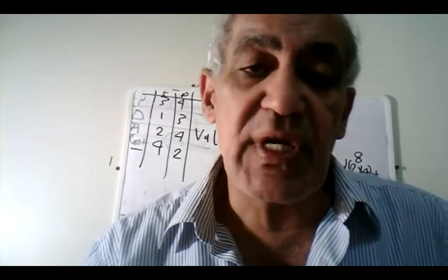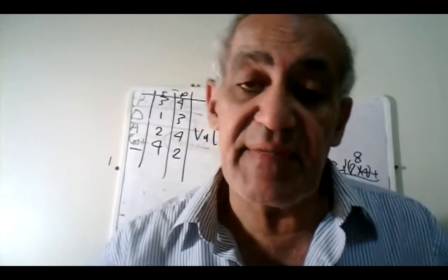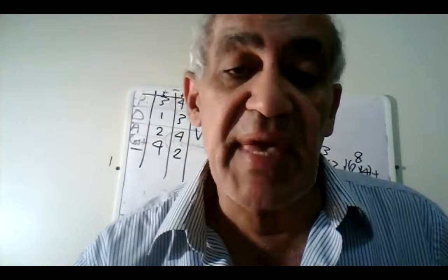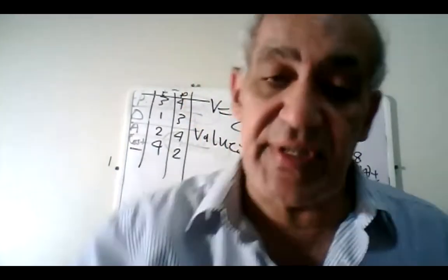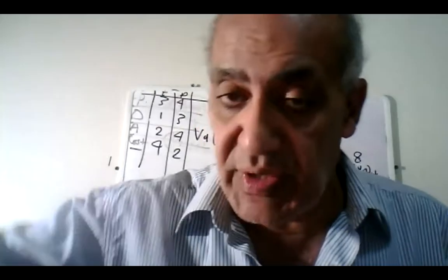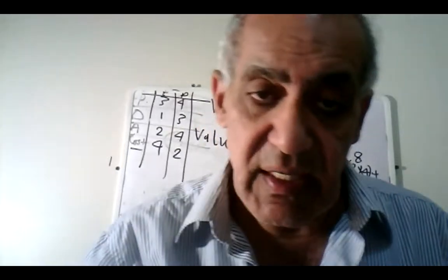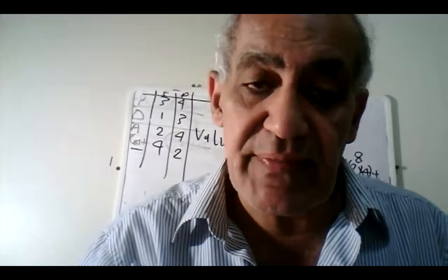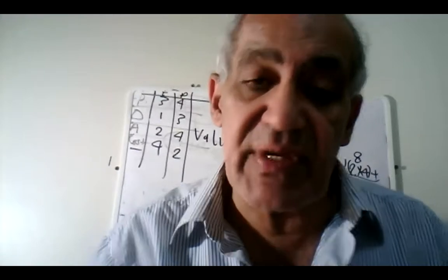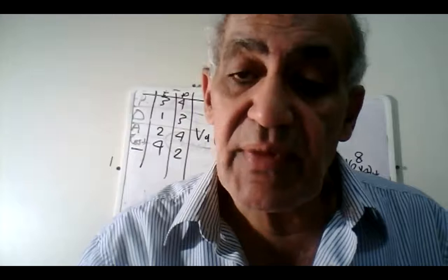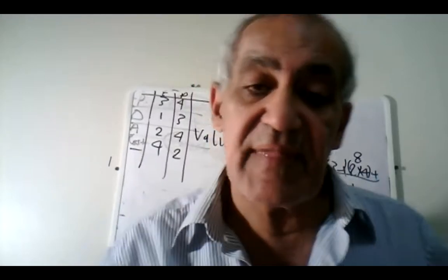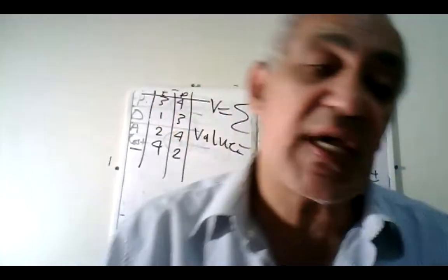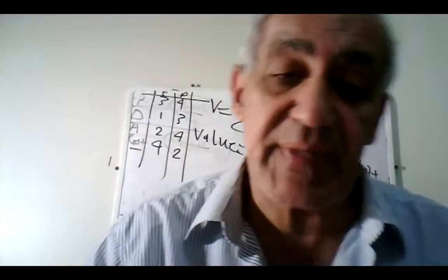We have also four levels of customization. Customizing means based on the order or the demand of the client. We have make to stock, products that require no customization because you will put them in stock. You will put them in the stores, the wholesale. Assemble to order means based on the order you have, you assemble your products that are customized only at the very end of the manufacturing process.